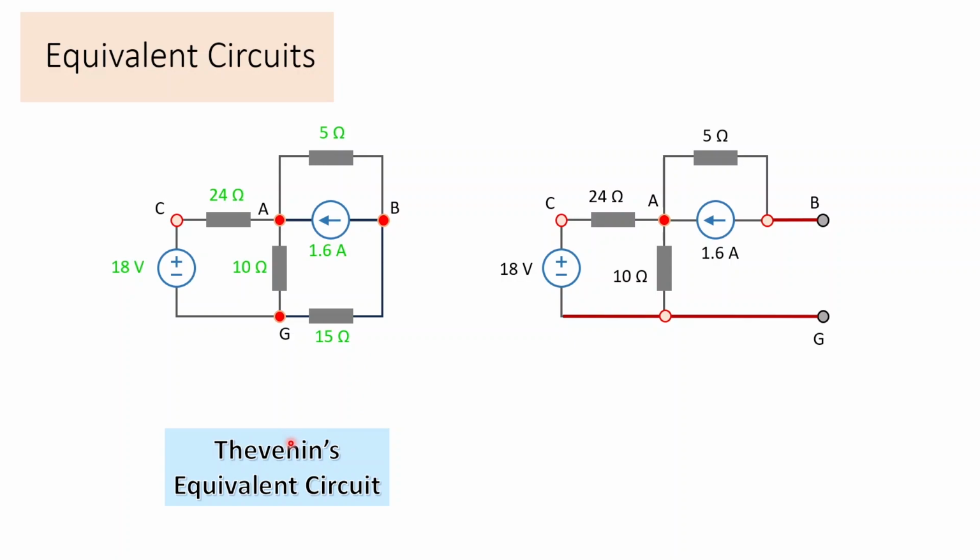So I want the current in the 15 ohms. With the Thevenin equivalent circuit concept, we would treat the 15 ohms as an output across junctions B and G, and that output is not shown. The rest of the circuit is shown, and the Thevenin theorem is that the rest of the circuit, missing the output, can be replaced by a Thevenin volts in series with a Thevenin ohms.